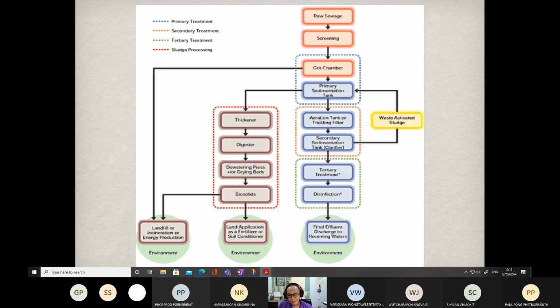Anaerobic process is a process whereby the organic substance gets degraded under the absence of oxygen in the reactor, so that this organic substance will be converted into methane and carbon dioxide, and at the end the sludge generated from the plants coming from the thickeners will be more stable, or becomes stabilized.